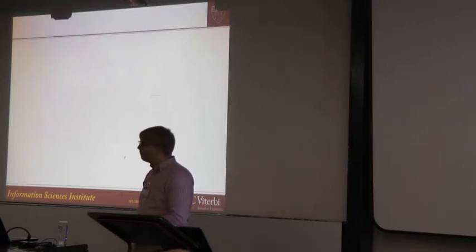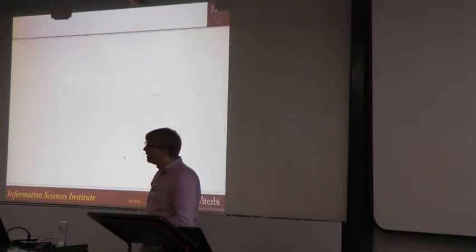Have you looked at the IP-XACT framework, which has sort of Eclipse plugins and synthesizers connecting up system-on-chip components in a similar sort of way? We're aware of it. I don't know, was there more of a question? Well, the question is, you're emphasising a particular application which is flowing between these components. So what does your infrastructure have beyond what you would have just for assembling the IP blocks on a chip, where some of them happen to be synthesized at the point of assembly, which is what IP-XACT does?